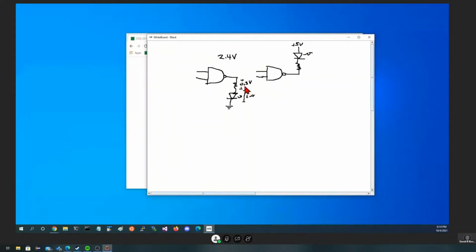Okay, well, on the data sheet, was 2.4 the value? What's the name of that value for this output? Should be V output low, right? Or V output high, one of those two. We're assuming this is the high voltage. For our data, the data we had is 2.4 volts. What's in the data sheet? Just pop your hand up real quick once you look it up. I don't have my data sheet handy. Robert? Yeah, VOH is 2.4 minimum, 3.4 typical. Okay, so it could be higher than this.